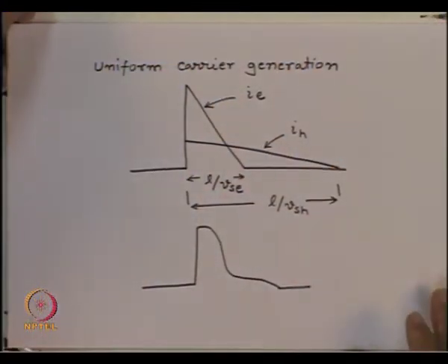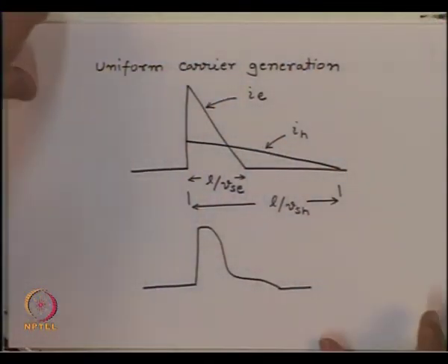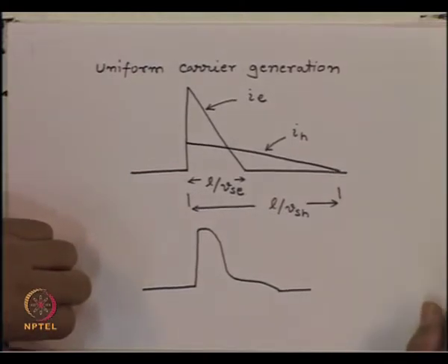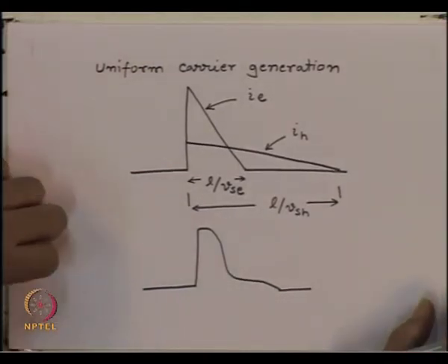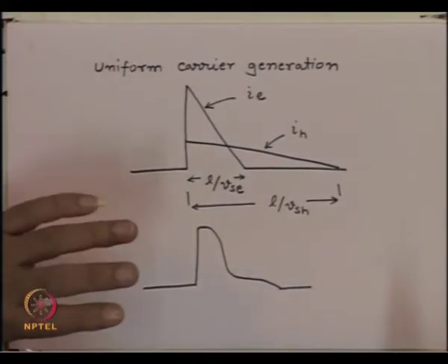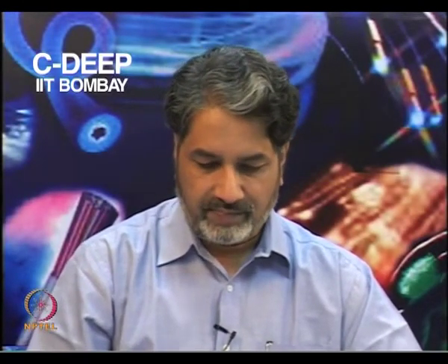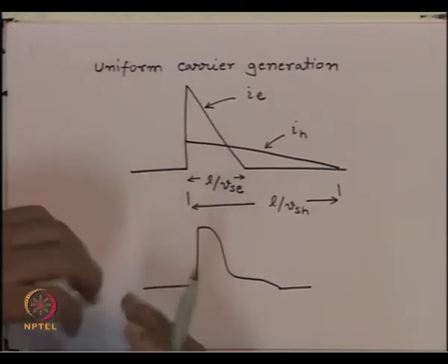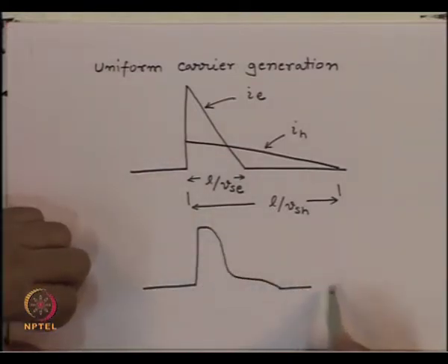So, we have some kind of pulse distortion which is going to take place during the detection process. So, this is one of the important aspects of photodetection, that when the light pulse is incident on the photodetector, the current pulse will have a different shape depending upon the absorption process and so on. Also, in addition to this, we will have the diffusion current, and since the diffusion process is a slow process, the diffusion current will keep flowing for a much longer time.